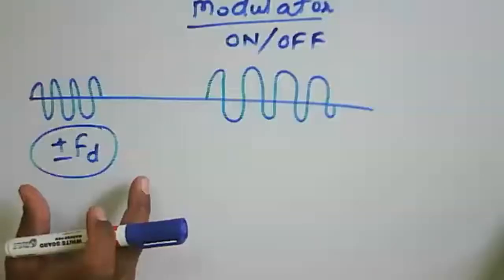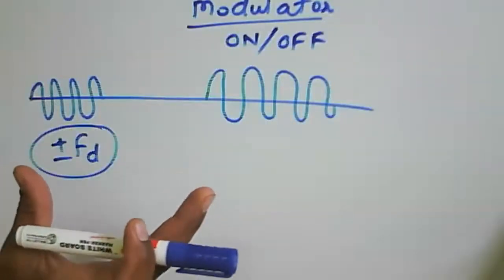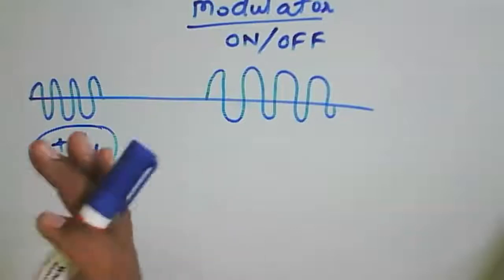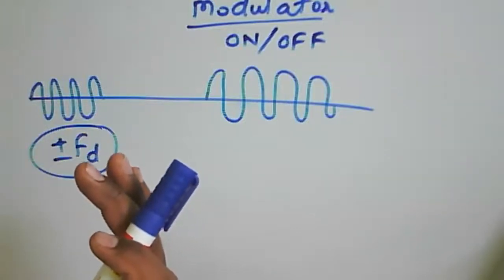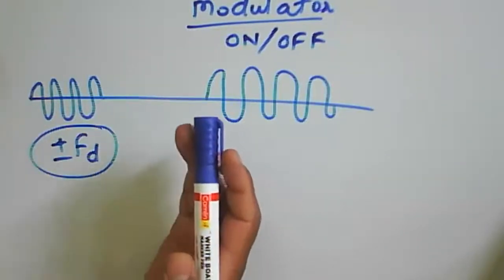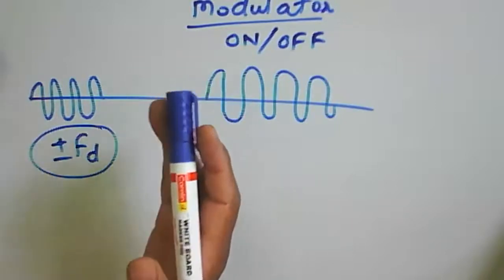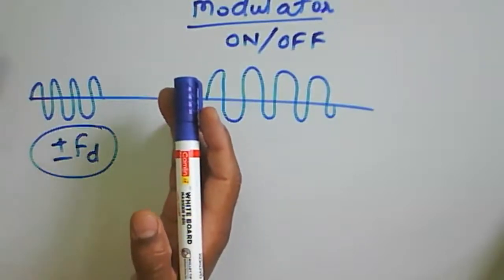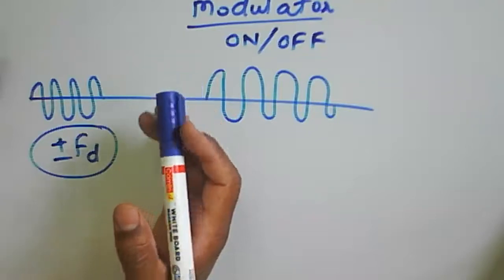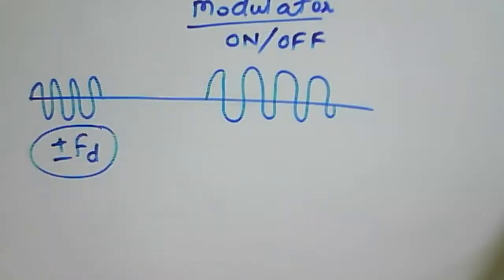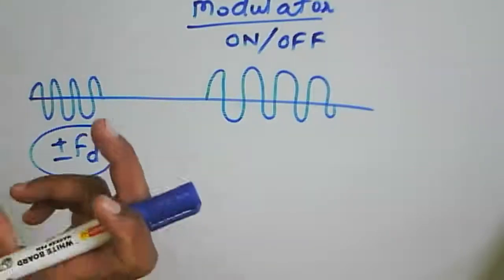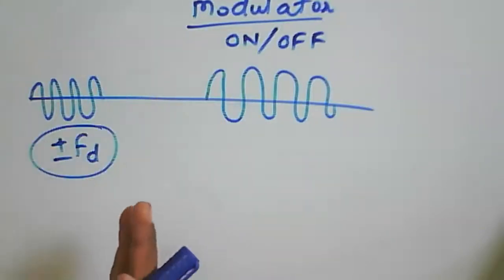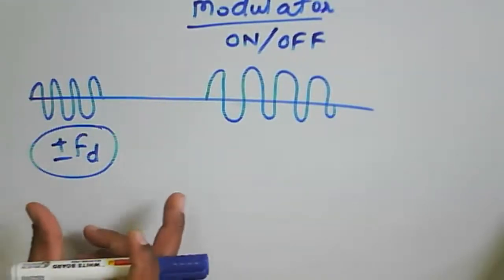Detecting the target depends on the Doppler frequency shift occurring. If that Doppler frequency shift is more than one cycle or less than one cycle of the train of pulses we have, according to that we are able to recognize the Doppler frequency shift.